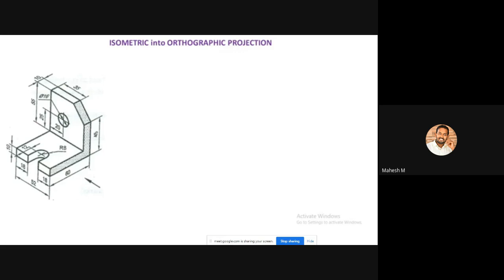We have discussed about this in our first unit itself. So we are discussing about first angle projections. In first angle projections, we have to draw all the diagrams in the opposite manner. Top view on the bottom, left side view on the right side, right side view on the left side. So as per our condition, we have to divide your drawing sheet into 4 equal parts. Like you can create a plus symbol on this diagram.